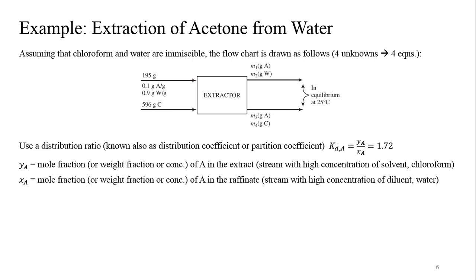All right. So how do we treat this? Well, one of the key aspects to doing any of these kinds of liquid-liquid extraction problems is we have to know something about how the solute partitions between the two fluids under equilibrium conditions. And a lot of times that's the tricky part. So that's where you'll have to go to a lab sometimes and collect data if it's not readily available, or you go searching for data and try to find it.